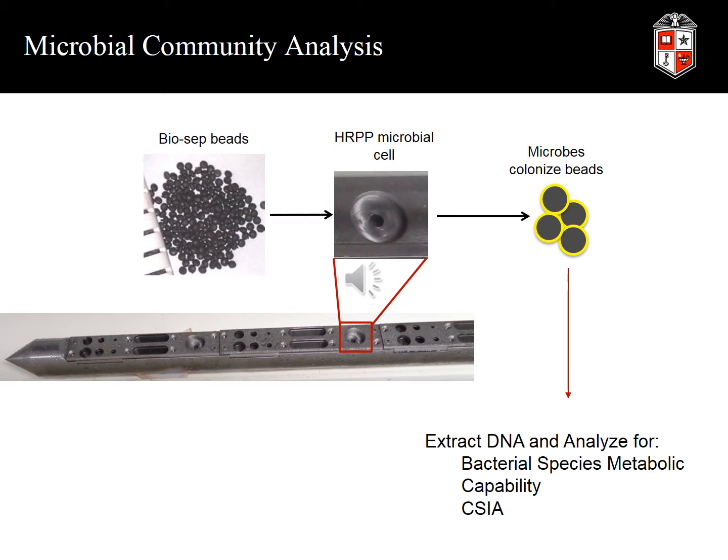One of our objectives in developing the sampler was to extend the capabilities of the traditional equilibrium pore water samplers. An important analysis that can greatly aid site evaluations is the knowledge of the overall microbial community and the activity of that community at the site. Typically this is done by placing a biotrap in a well and then analyzing the bacteria that are captured on the biotrap. But again, the well is going to return information on the most permeable region, and it can be very difficult to get sufficient water in very low permeable regions.